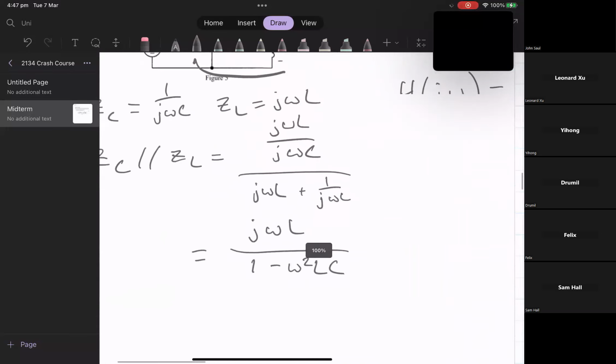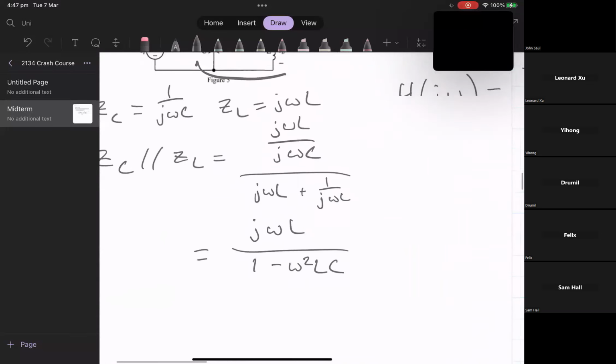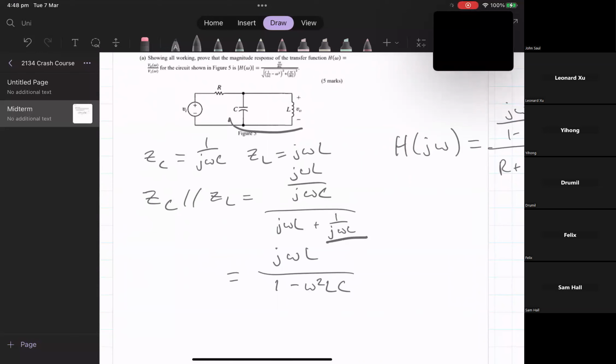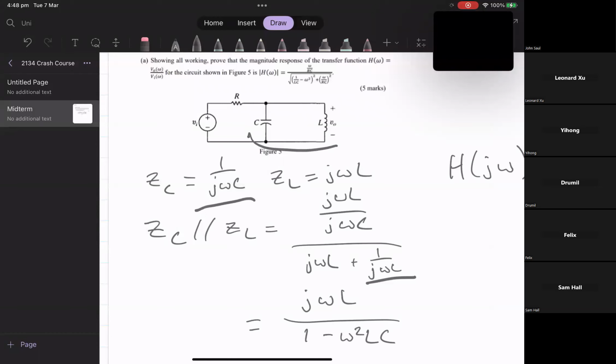So we're multiplying by j omega C in the bottom, and that moves this term up here. So we just get j omega L. This is 1, j times j is -1, the omega is squared LC. And that should come out. First step, deriving 1 on j omega C and j omega L. Yep, that's just our formulas for impedance, capacitance, and inductors.